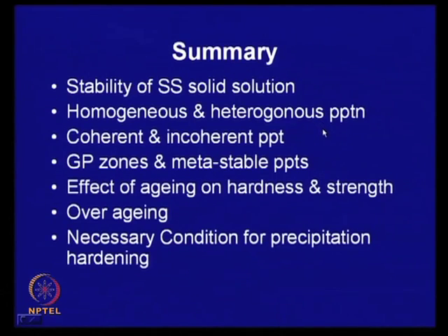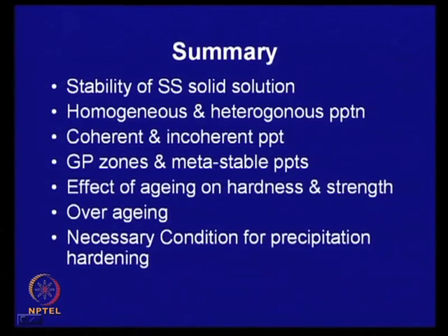The grain corners are the most favored, where 4 grains, in a 3D network, meet in 3 dimensional space. These are the places where if a precipitate forms, there will be minimum disturbance and the lowest surface free energy change. So, they will be the most favored site. Next will be the grain edge and then the grain face.